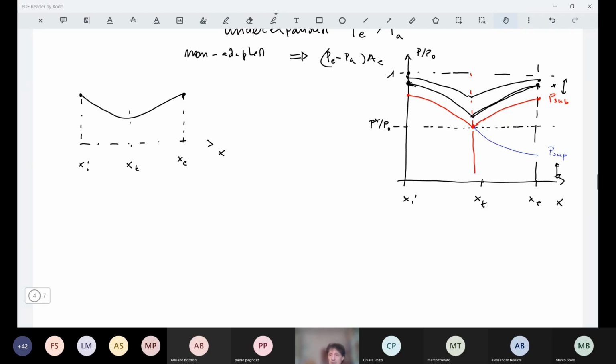That means that we have supersonic flow within the diverging part of the channel, and we have here a supersonic jet that, if we consider pressures lower than this one, is the same that we have seen for the choked converging channel, when we have pressure lower than the critical one. So here we have something which tells us that the nozzle is underexpanded, and there will occur something outside the nozzle that will adjust the pressure to the ambient.